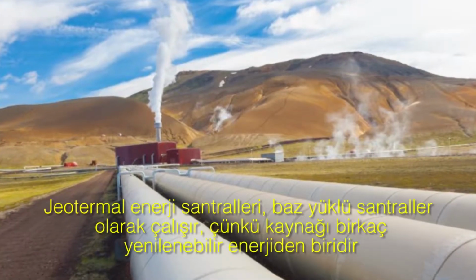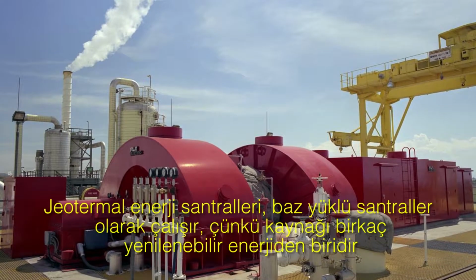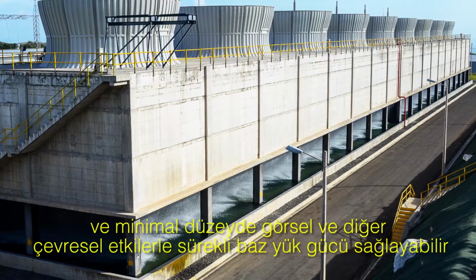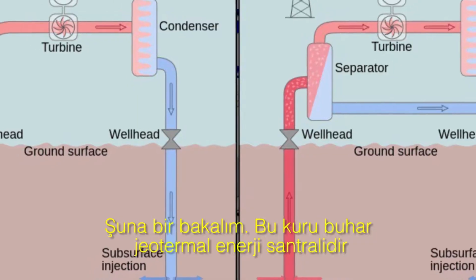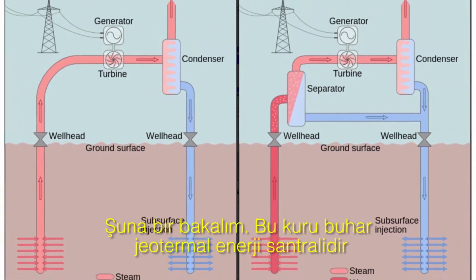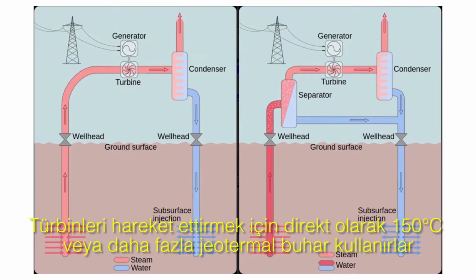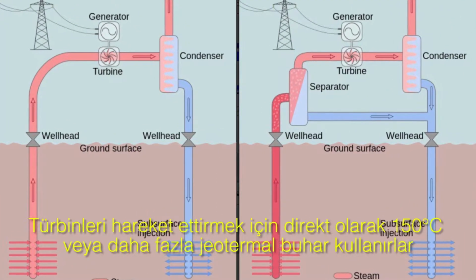Geothermal power plants usually operate as baseload power plants, since its source is one of the few renewables that can provide continuous baseload power with minimal visual or environmental impact. Have a look at this. It's a dry steam geothermal power plant. They directly use geothermal steam at 150 degrees Celsius or more to move the turbines.